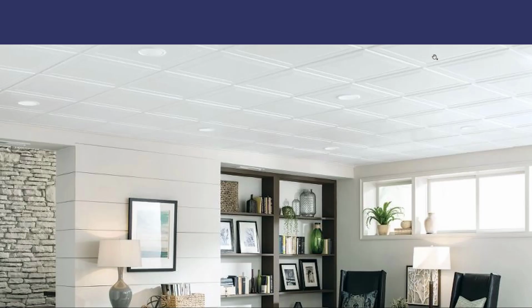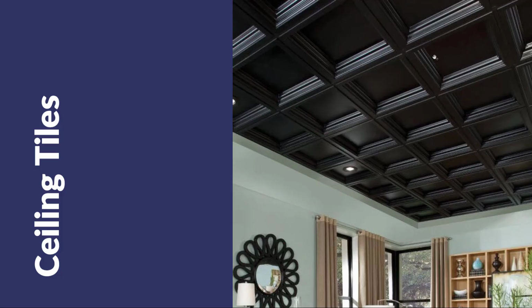So here's an example that is extremely simple, white, and sort of you just don't really think about it too much. And this is really commonly done as a cost-saving measure, especially if there's an old plaster ceiling or something behind it that was breaking down. This could actually be installed over it. They can be installed for acoustic reasons. And sometimes they're installed because you can actually create a gap between the ceiling and the structure above that you can put in HVAC, so the ductwork that you need, or lighting, things like that. You can actually pop these tiles out and then access those systems.